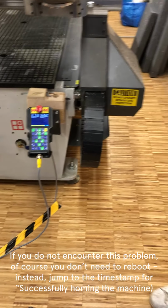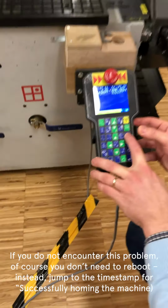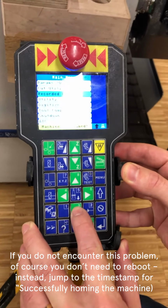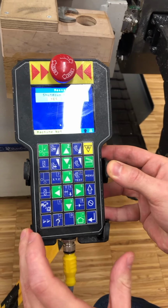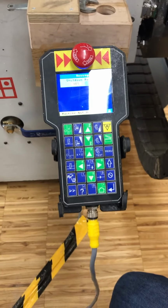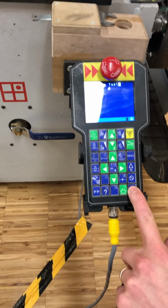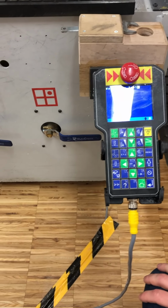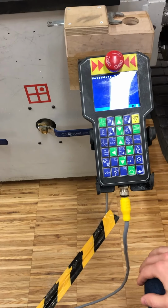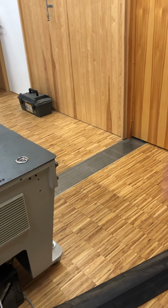So okay, you turned off the power. One can only shut down the machine after you press menu and go down to shut down and confirm shutdown. So we can actually do this now, when such things happen. Then we say unload tool, and it finds that it doesn't have any tool, so it will not do it. Motor drive disabled. Now it's okay to power down. It's very straightforward, because it's the same way that we turn it on, but the other way around.